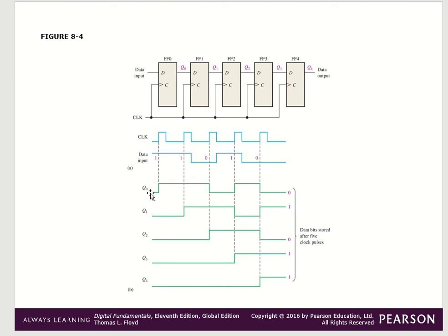So what is this waveform? This is exactly like the D flip-flop output. This one we already studied before, how to draw the output of the D flip-flop. Repeating again, very important. If you know this one, all other things are very easy. Shifting is very easy. You just need to know how to draw this one like a buffer. Assume that this is a buffer.